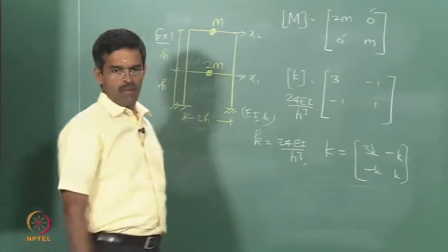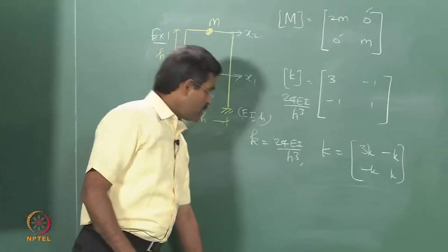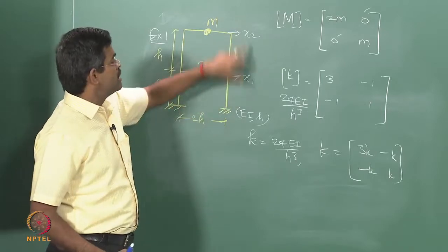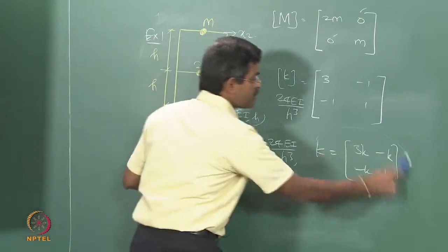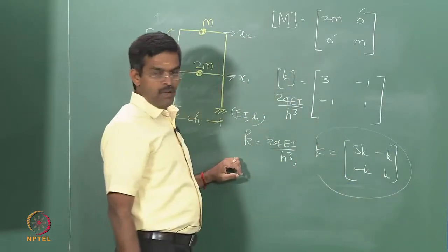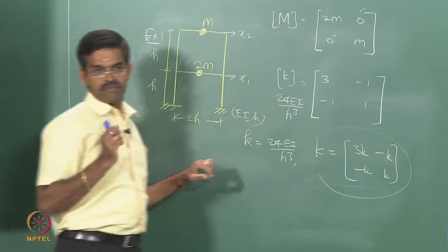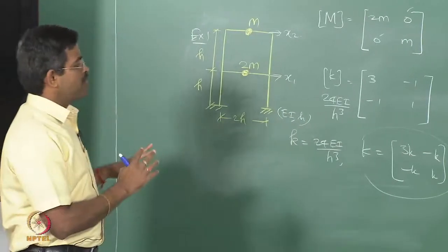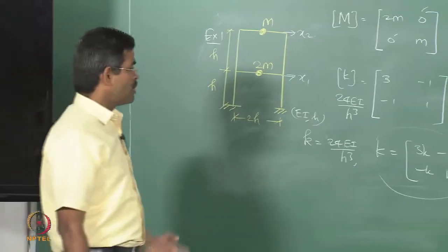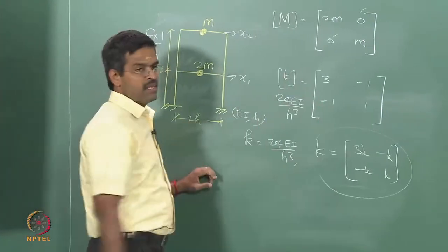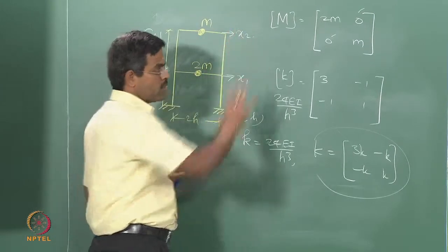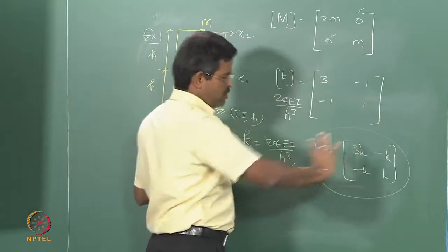You will again notice here that since stiffness is not at the point where the degrees of freedom are marked, the stiffness matrix is in total, it has a larger leading diagonal and it is symmetric. These are classical observations which you must keep on repeatedly observing when you write these matrices, so that you know that you are not making any mistake, and you will also know how carefully you will select these degrees of freedom, so that they automatically get formed in a normal generation.